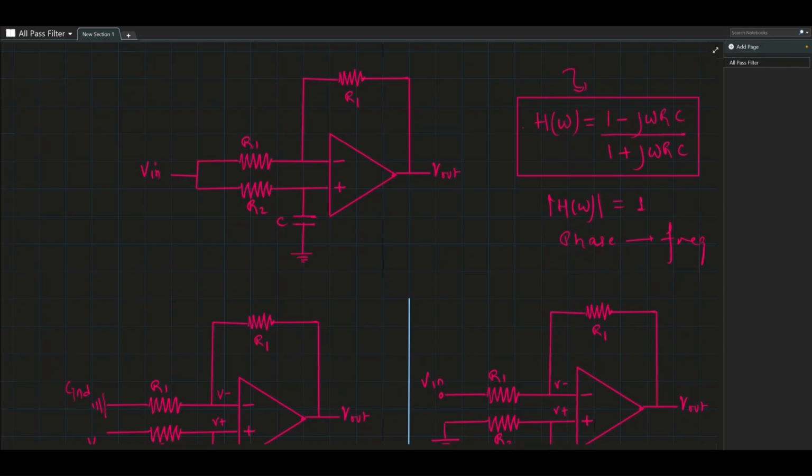an electronic circuit. Here we have an op-amp circuit, and let's see what kind of function this op-amp circuit generates. It's a pretty simple circuit. On the inverting input, I have 2 resistors connected. One is this input R1 here, and then there's another one in the feedback path, R1. Both of them are the same value, so the output gets fed back to the input.